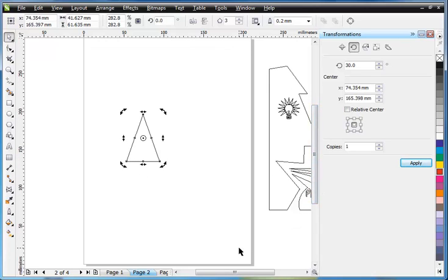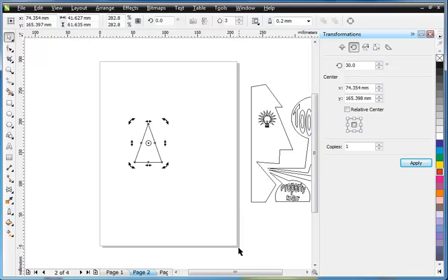When it's deactivated, the X position is determined by the document axis. So, it starts right here in the bottom left-hand corner of the document, where there's 0 on the left-hand ruler. Let's test this. Change the X and Y axis to 0. As you can see, the rotation point was moved to the very beginning of the axis, in this case, the bottom left corner of the document.